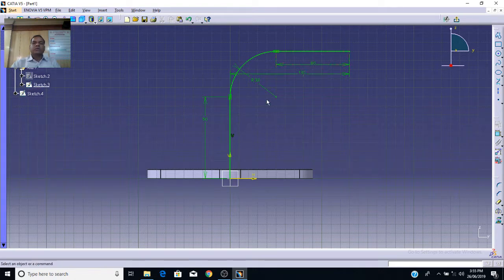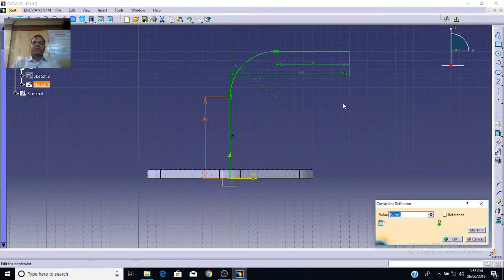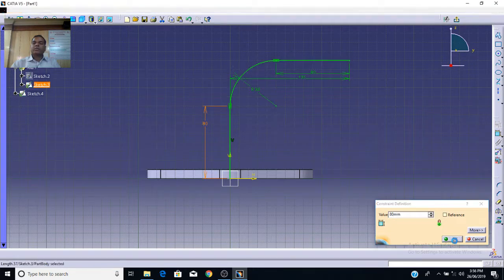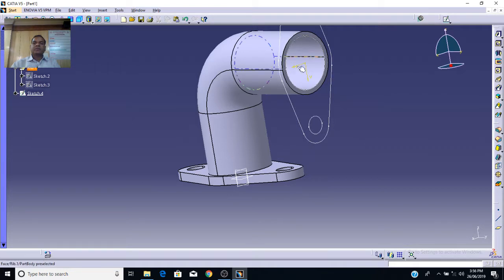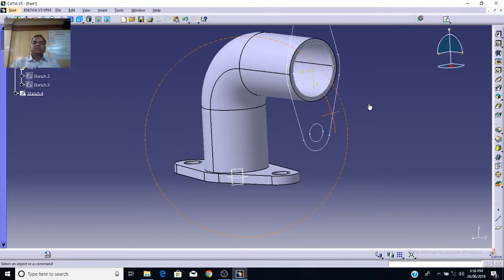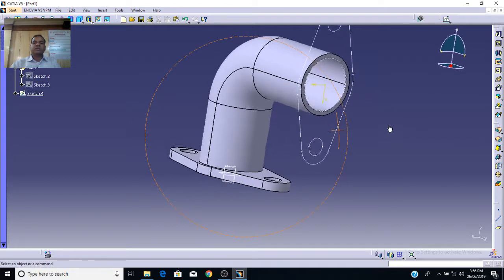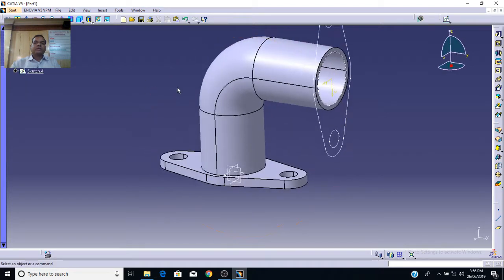If you change it and make it 80, your problem will get solved and your sketch will match exactly. So, check that in such cases, if you want to copy the sketch, then these two lengths must be equal, as we have made one mistake in our case, that is why it was not matching.